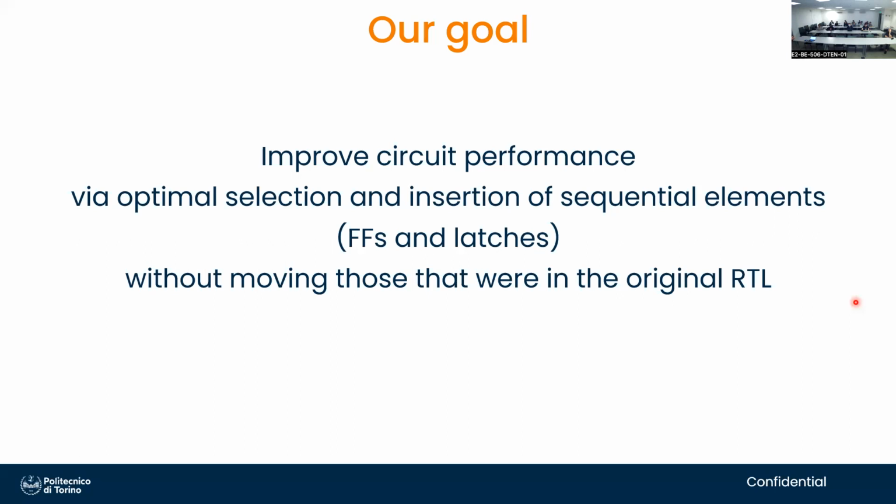So the goal of this work is to improve digital circuit performance, clock frequency, by selecting the kinds and choosing the locations of sequential logic elements, starting from an existing digital design coded by a human or by high-level synthesis in synthesizable Verilog or VHDL, with an important constraint that wherever the designer had placed initial flip-flops, we will still keep one memory element, could be a flip-flop, could be a latch, in that same location.